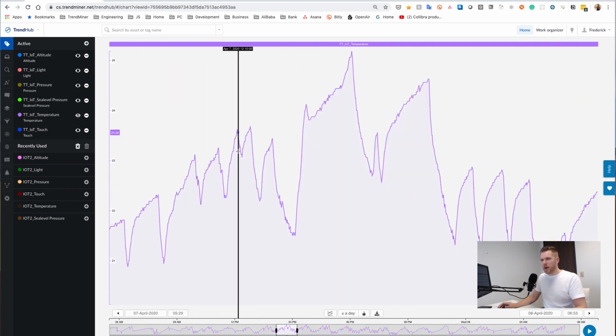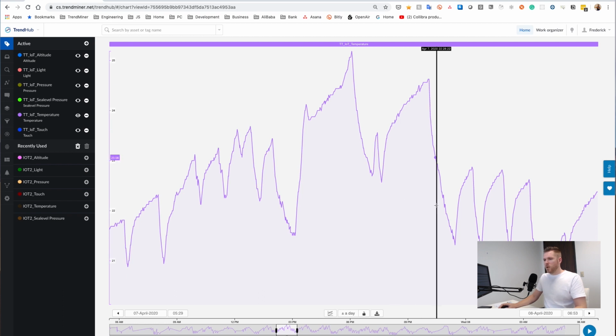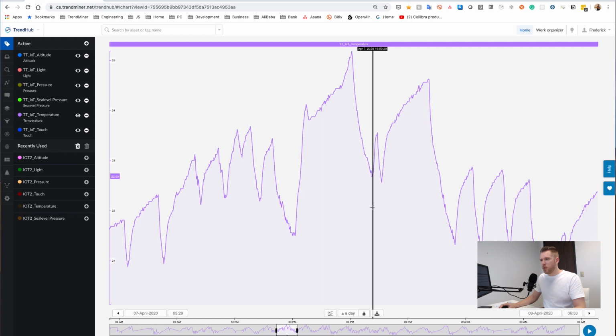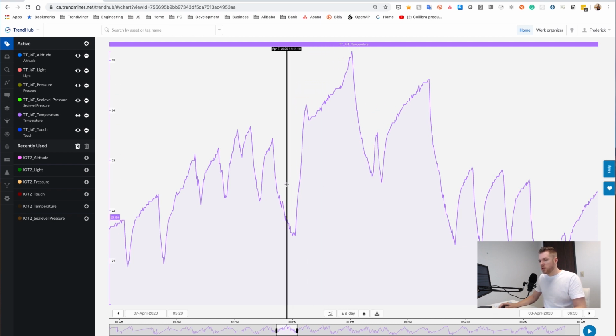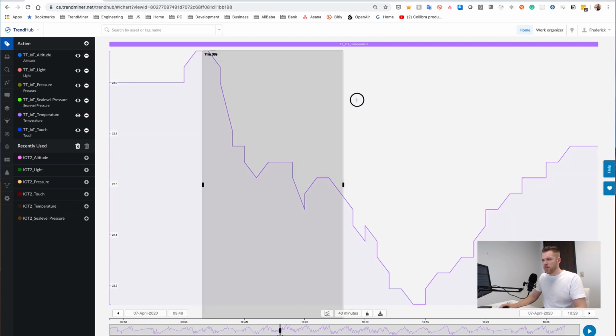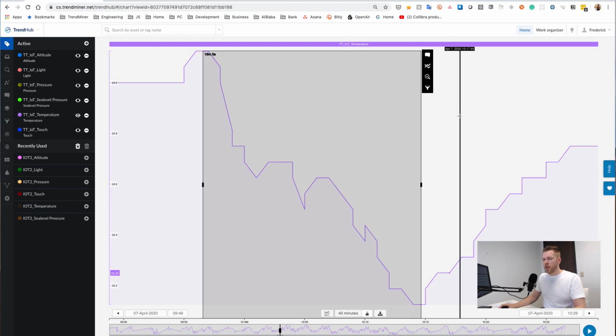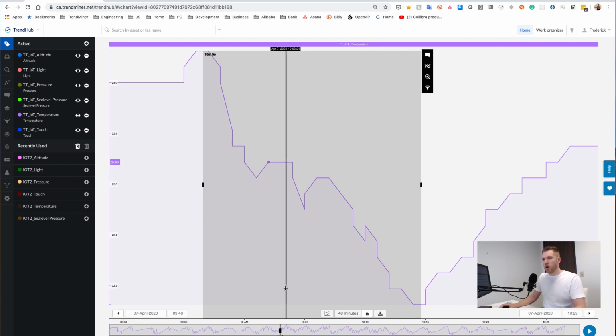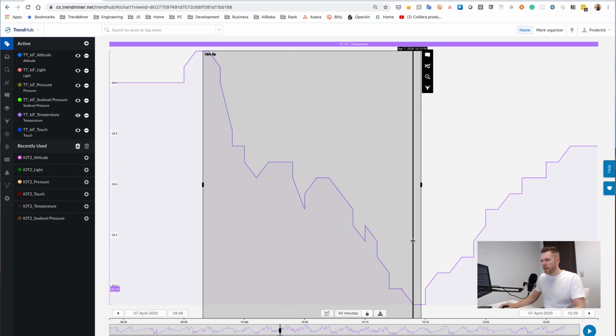Now, if I zoom into a particular day of temperature readings, you very clearly see this kind of sawtooth pattern, or the sawtooth behavior, which is what I just explained. So whenever we are outside of the set point range, the Google Nest will trigger air conditioning, and this will then trigger a quite intense period, about 15 to 20 minutes, for example, here, where cold air is being blown into the living room to get the temperature back down.